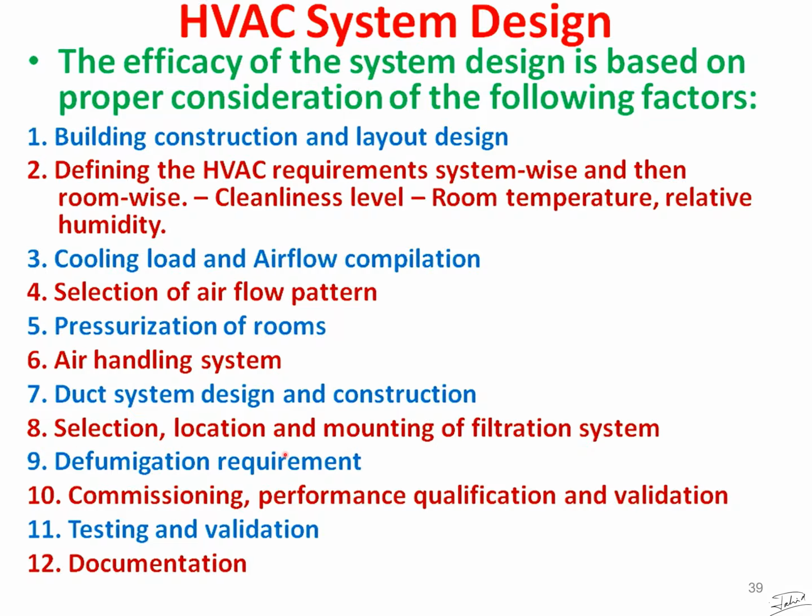After that, selection, location and mounting of the filtration system, fumigation requirement, commissioning, performance qualification and validation are required, that is, whatever you have already designed and constructed, what would be the qualification of these, and what would be the validation pattern of this. You have to do this at the very last stage, testing and validation, and finally the documentation. Okay, these are the step-by-step procedures for HVAC system design.